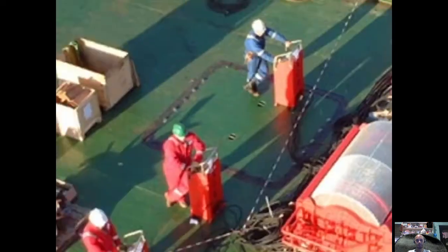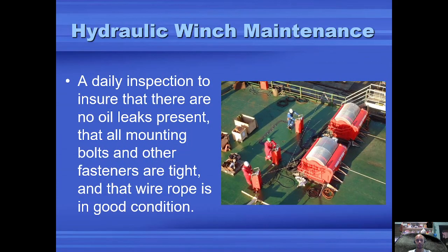Next we have hydraulic winch maintenance. Do a daily inspection to ensure that there are no oil leaks present, that all mounting bolts and other fasteners are tight, and that the wire rope is in good condition. Usually our wire ropes are maintained or greased by the deck personnel.